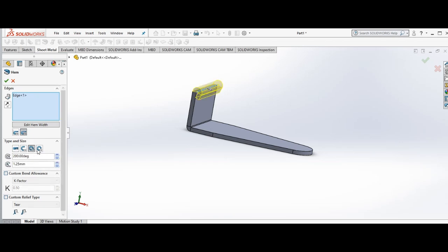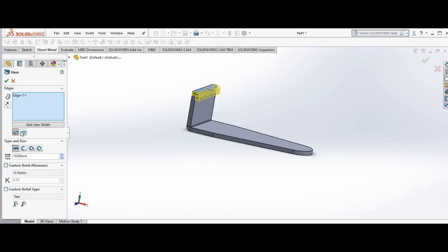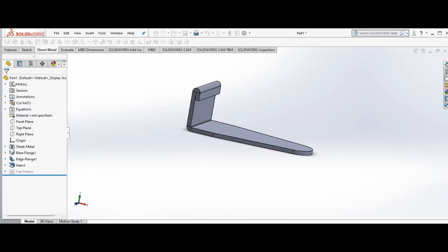Now let's select different types. This was not showing. I think I prefer this type and size. No, this one will be better. We leave the hem direction. Assuming we make it 20, let's see how it looks. We'll make it 20. Press enter. See, it's longer, so let's make it 15. We press enter. I think we have something good there, and we click OK or close dialog box.